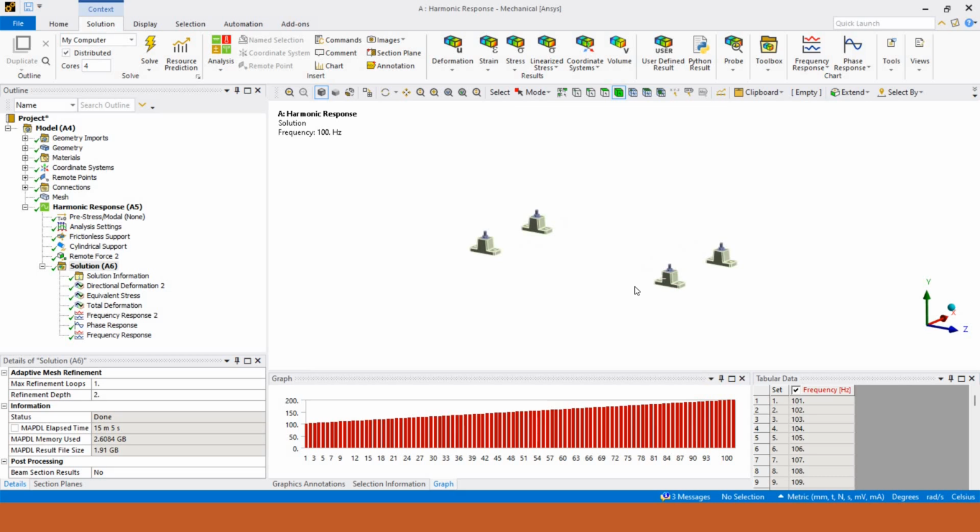Whatever the model, whether it is complex or simpler, you can follow the similar methodology. Here you can either model the complete split AC, then create the support, model the support, and consider the maximum weight, or else you can use the simplified four dampers, or else you can use a simplified single damper with the force divided by 4. Likewise, there are different possibilities to perform the simulation. The ultimate purpose is to get the proper result. So that's it for the present chapter of harmonic response analysis.